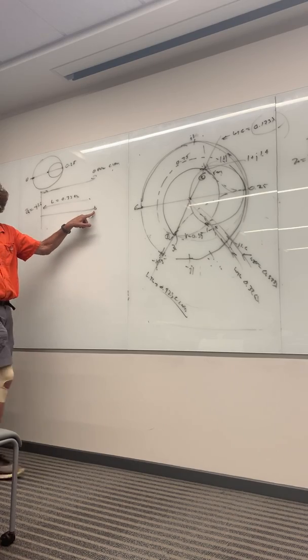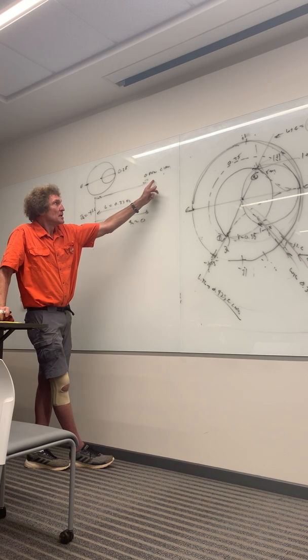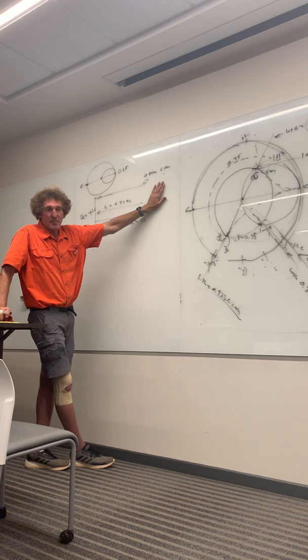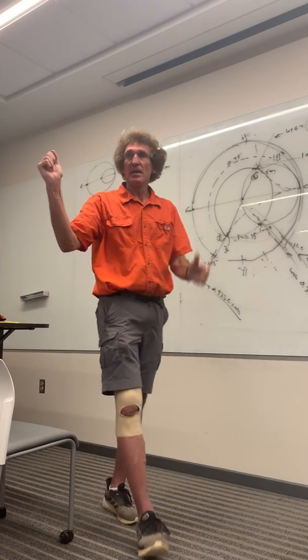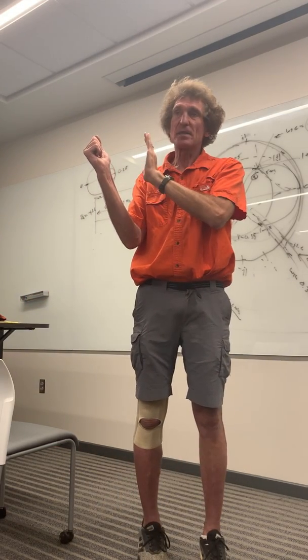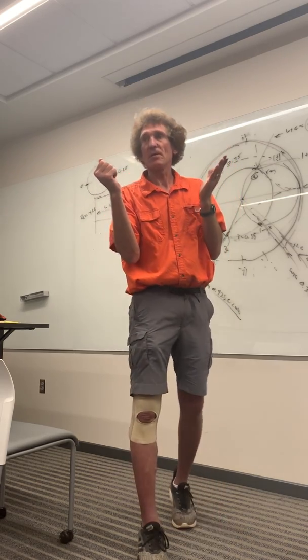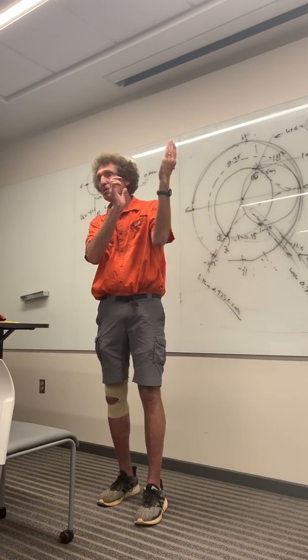Now, when you're on the board, that is something that causes an electric field that could easily penetrate, it could corrupt a circuit next to it. It can actually be felt by the circuit. It's a near field electrical field. It's not propagating, and you know, have you ever done the thing where you rub a balloon on your head? And as you get near there, you can actually feel the static electricity. It's not a propagating field, but what you're really feeling is an electric field, all right? When the hairs of your arms stand up and stuff like this, because it's very close to the actual source